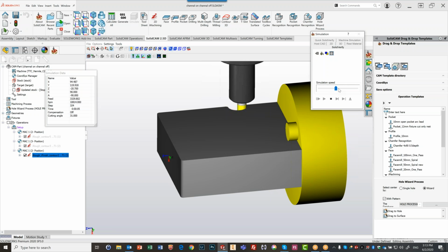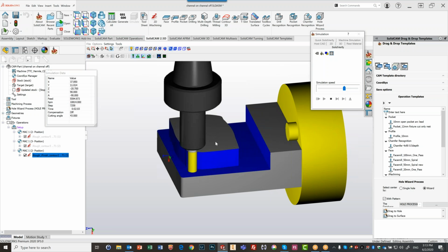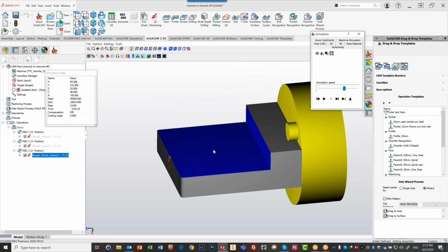It creates the moat that I talked about, between the wall and the rest of the material, and now it's doing that morph spiral around it. Because we know the spiral is the most efficient way of cutting, and we talked about this last week. In order to do a morph spiral around this, however, we had to first create a channel or a moat, as you may have it, to separate that area so we can work around. Okay, that's excellent.